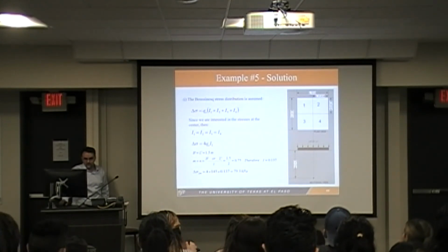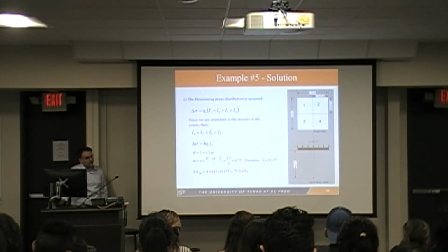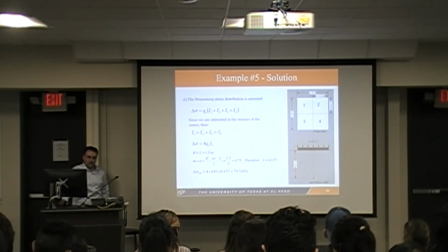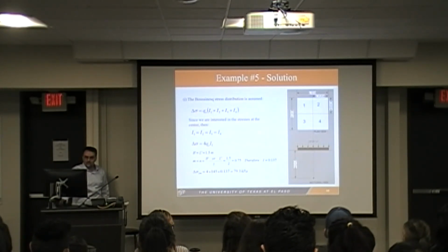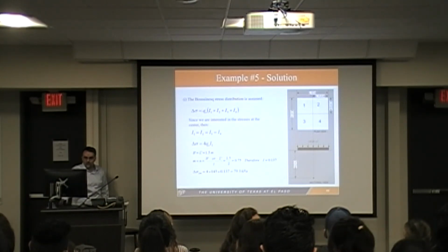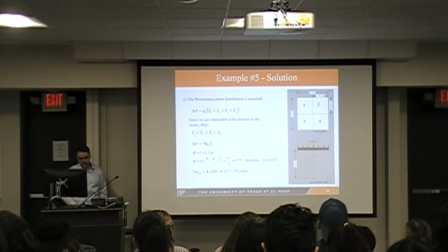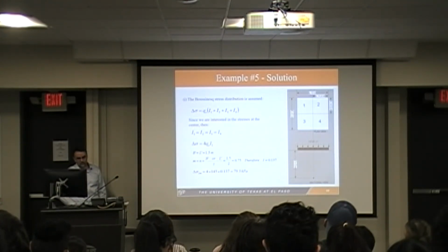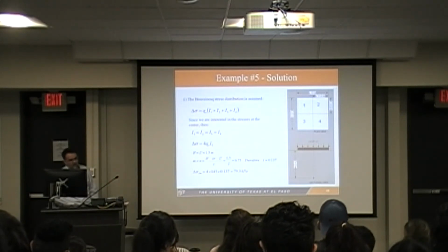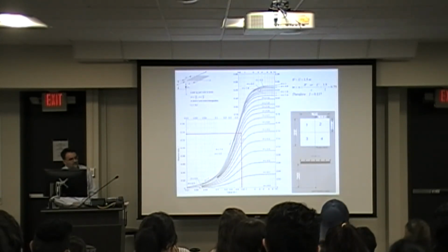This would be delta sigma equals the distributed pressure times the influence factor associated with each of those segments. Because these segments are similar and equal to one another, that would be 4 times Q naught times one of those I's. And notice the values. If you do the calculations, 4 times 145 times 0.13 ends up being 97.